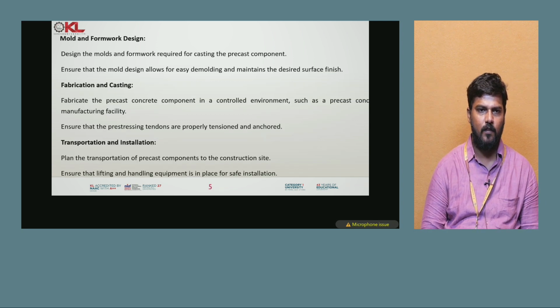Next one is the mold and formwork design. Design the mold and formwork required for casting the precast component. Ensure that the mold design allows for easy demolding and maintains the desired surface finish. Next one is the fabrication and casting. Fabricate the precast concrete component in a controlled environment such as a precast concrete manufacturing facility and ensure that the pre-stressing tendons are properly tensioned and anchored.